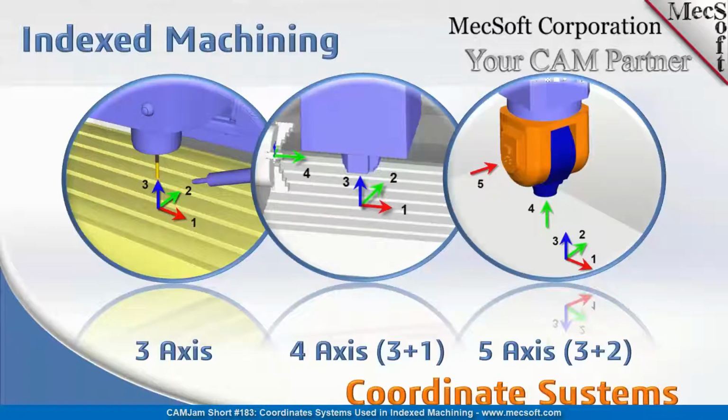And then 5-axis indexing, or 3+2, very similar, where 3 simultaneous axes can move, which basically would be 3 linear axes moving, and then you have 2 rotary axes that can be rotated and locked. So we see it as 3 distinct classes of index machining, and we have options in the system to enable you to do all 3 of these types of machining.